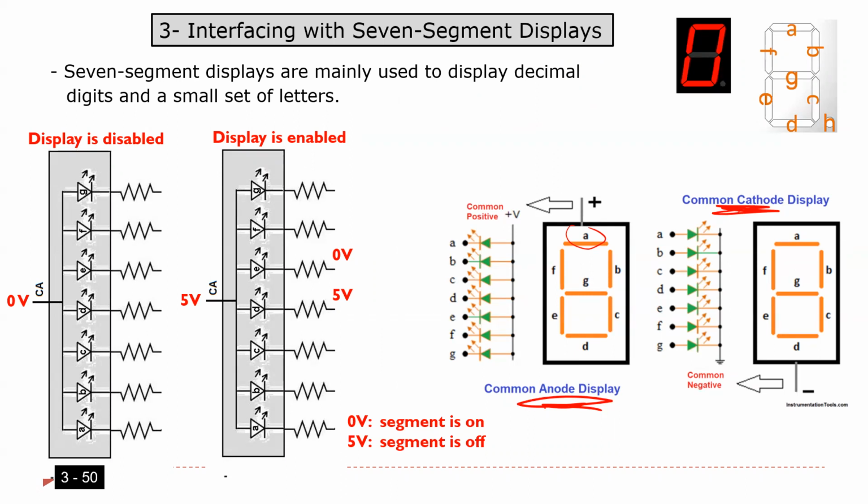I'm going to tell you the difference. In the case of common cathode, as you see here in the figure, every segment is 1 LED, as I told you. In the case of common cathode, they connect all the cathodes together, and that gives you one pin here. So if you buy this 7 segment, how many pins can you find? We are going to have 8 pins here, including the dot, because there's one for the dot here. Also, we have another pin here for the common cathode.